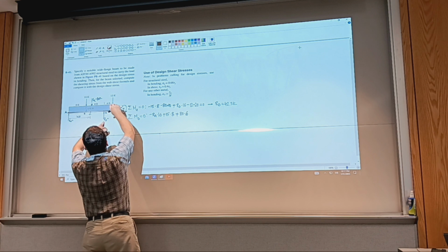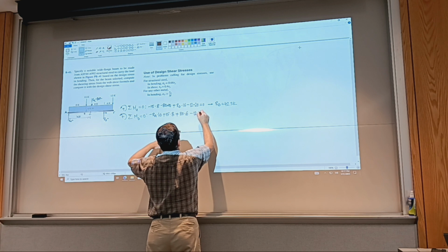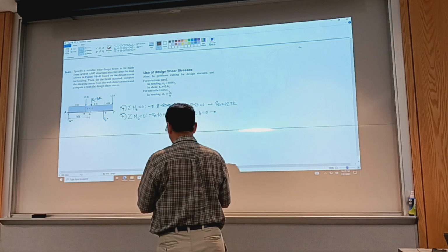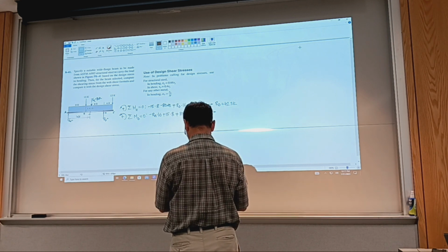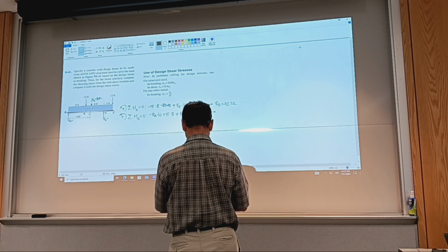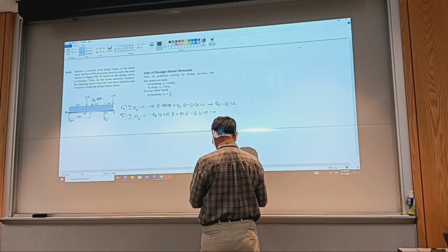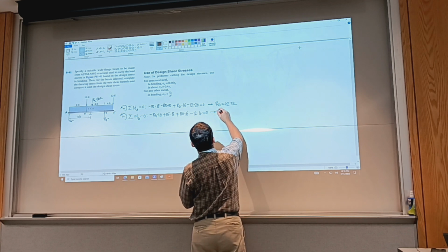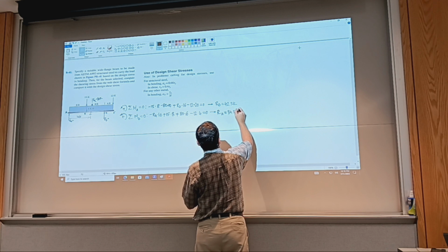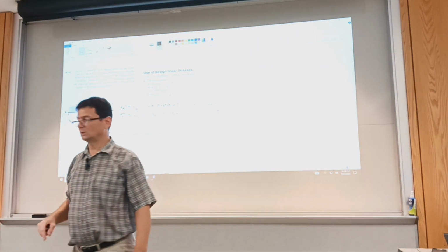And then I have another negative moment caused by the 12K, arm is 4, equals 0. All right, so RA is 15 times 8 plus 80 times 6 minus 12 times 4. And this is 552, and then divided by 16, that's 34.5. So RA is a positive 34.5 K, and it's expected. Both of them should be positive to resist only downward loading.